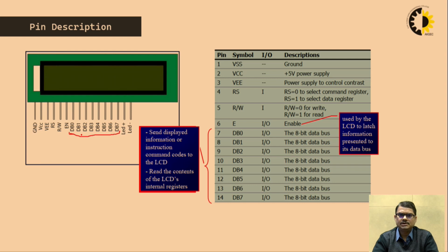But for practical use, if we are using 8 data lines to interface a microcontroller, and in our project there may be some more devices which we need to connect with the microcontroller, then there may be a pin crisis. To avoid this pin crisis, we can write data onto the displays in 4-bit format. For that, we have to do certain manipulations with the data, and that is the packed BCD and unpacked BCD manipulation I am going to talk about.